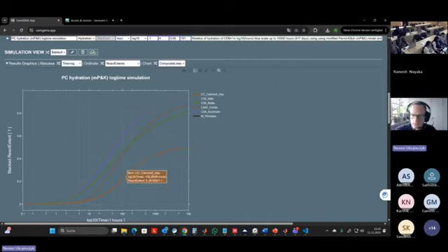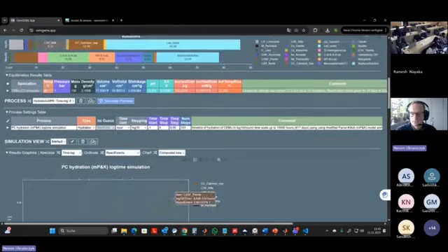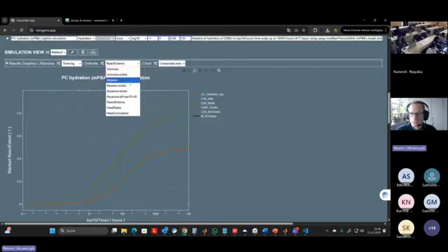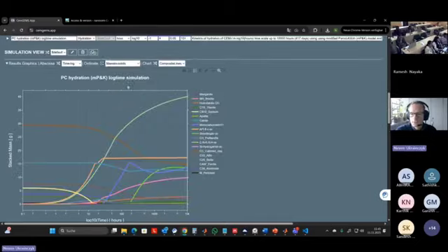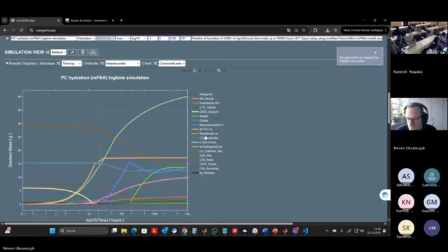So if you have your fly ash, you did your TG measurements, you know your reactivity of pozzolans from the TG, from the portlandite content, then you can calibrate your model result to fit your amounts of portlandite, which you can find here. Where is it? Very little. This is the portlandite.